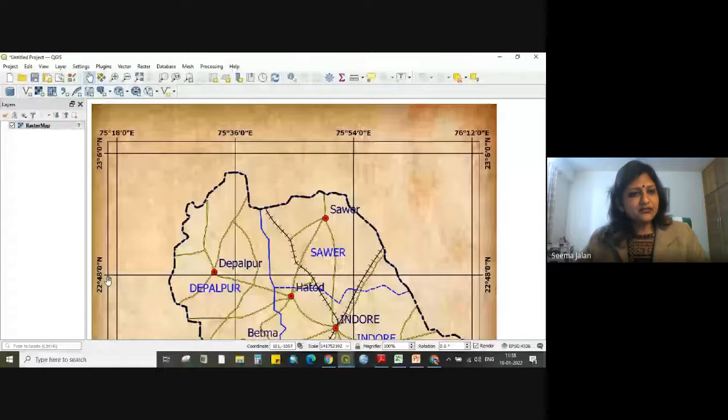So I have to establish a link between these page coordinates and these real world coordinate values so that for every single pixel in this map, my GIS is able to link both of them, and wherever I take my cursor, it is able to understand what real world coordinates are there for this particular point location. Okay, so I have to establish that link.